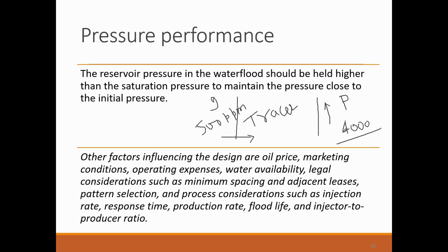So the day you see that the 4000 ppm obtained from the produced water is reducing in a particular trend, or the water cut of this producer well is increasing, you may get some indication.